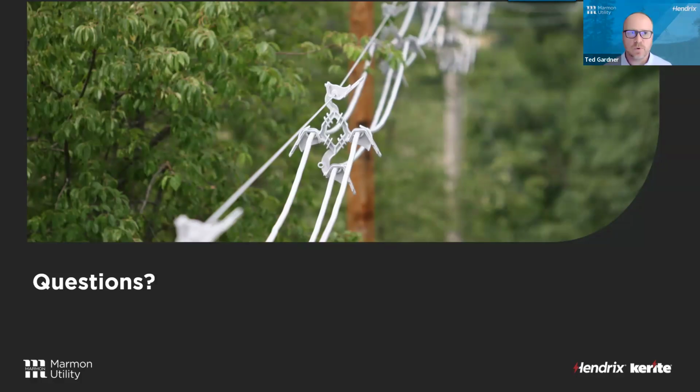One of the issues with tree wire is the supporting structure and equipment for tree wire is basically the same as it would be for bare wire. Your dead end shoes that are attaching directly to the ACSR are going to be the same, but you're just adding a covering kind of mid span to that. So you've got a bigger surface area, you've got more weight. It's almost like you're derating it as it's installed, and then you add more ice and wind loading on top of that.